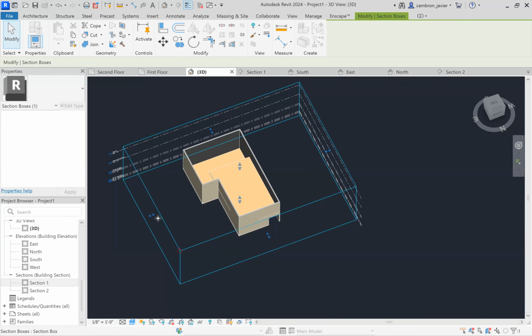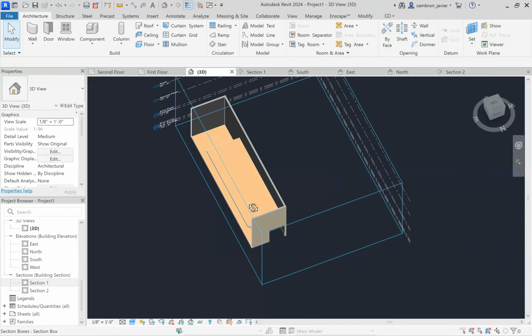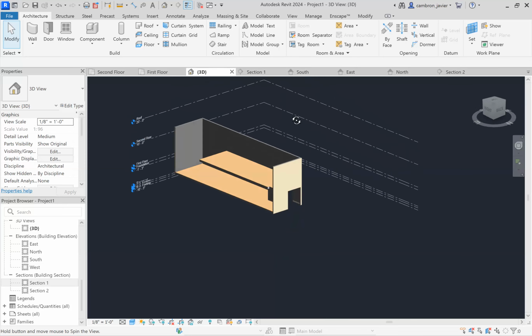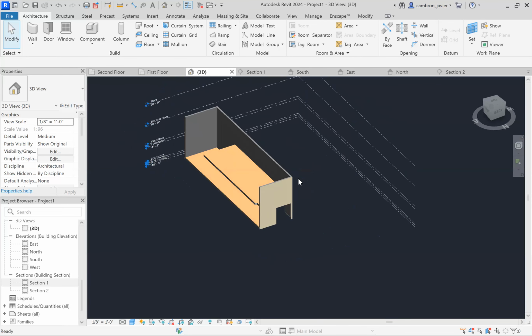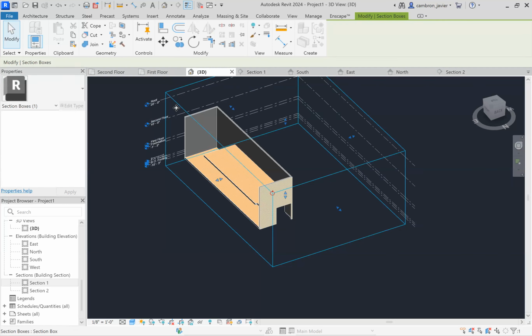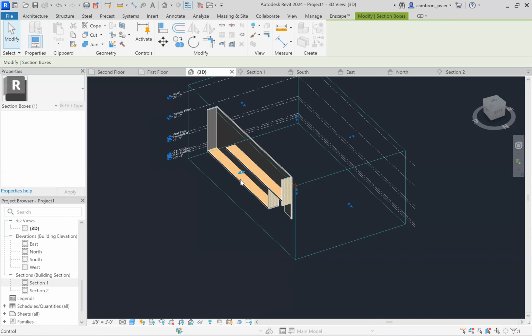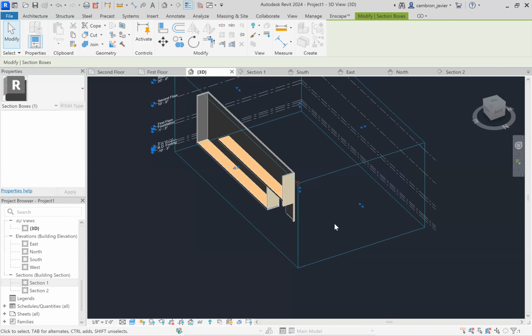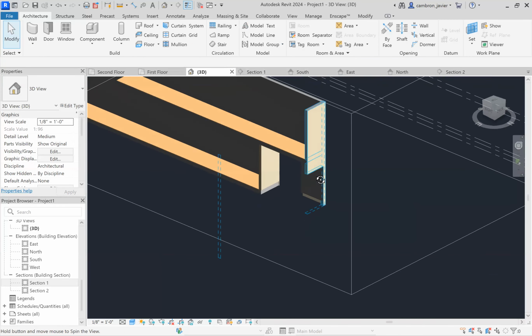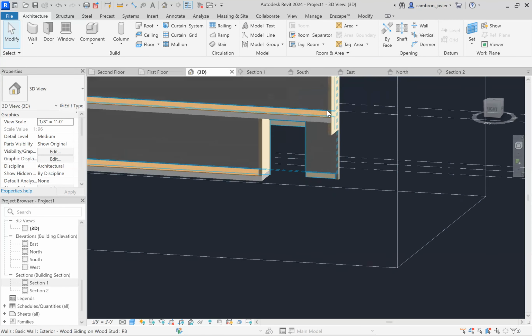I could click on the box, and this box has these pull arrows. So I could click, and I could also move this just like that. And it cuts a section in the 3D model, right? So if I'm still not understanding what's going on in the section, I could come in the 3D view, do the section box, and just kind of roughly guess where my section is being cut from. And now I could take a look and be like, oh, that's what's going on, right?